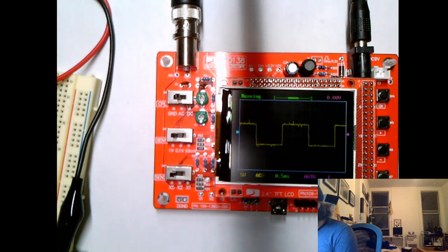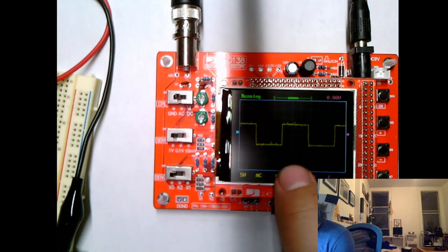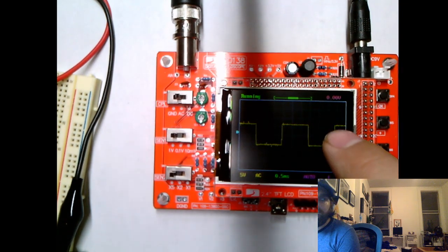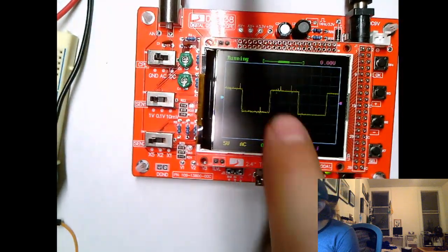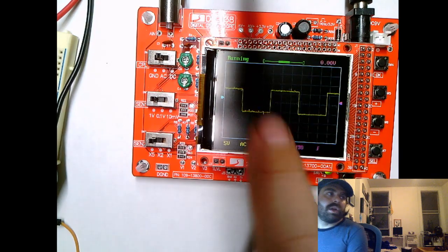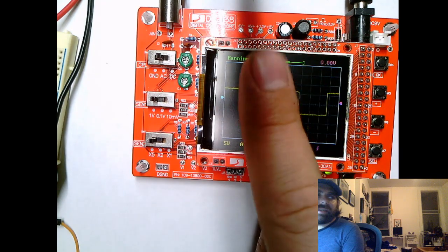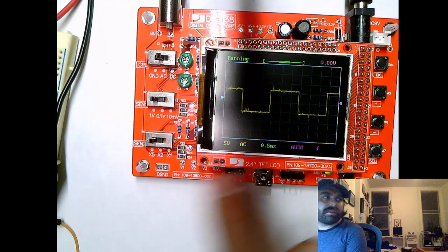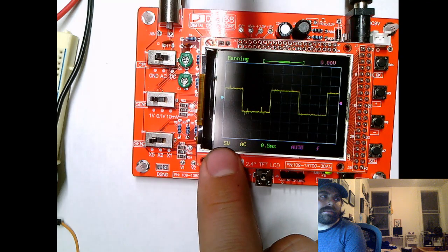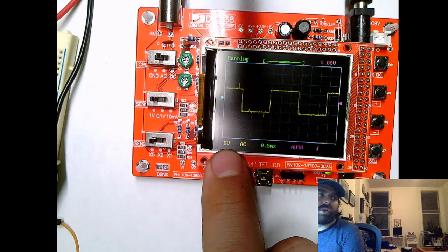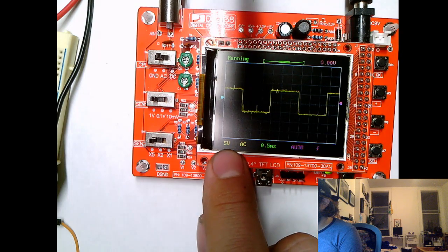So it looks like this square wave is just over 5 volts. I don't know if you can see it on the camera, but on this oscilloscope, I'm just above the first demarcation line. So our vertical axis is telling us how many volts the signal is, and down here, each division is this many volts. So this is 5 volts up and 5 volts down.